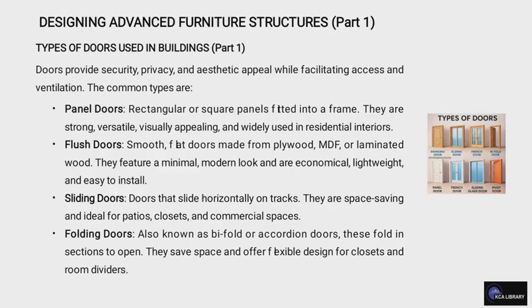We have the flush door, and this is a smooth, flat door that is made from plywood, MDF, or laminated wood, and they feature a minimal modern look and are economical, lightweight, and easy to install. The next is the sliding door. These doors slide horizontally on track, and